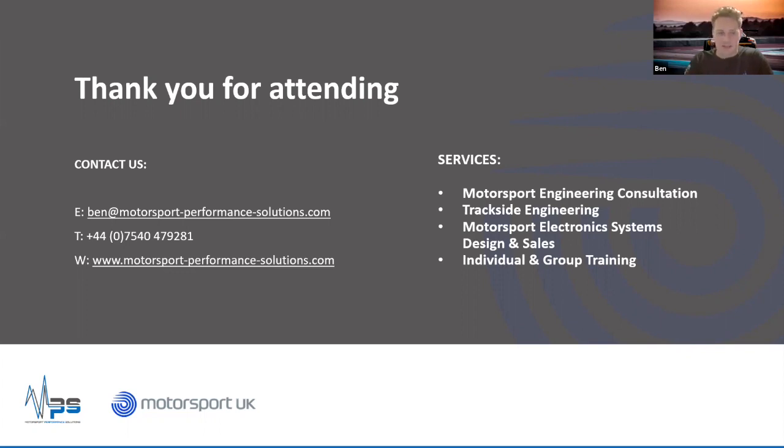But as someone that's sort of the intended audience of this, people that have never used driver data or any sort of data analysis before, you don't have to worry about being that accurate to still be able to productively use the results, if that makes sense. So the key thing with mounting, though, is to ensure that the accelerometer can't move, which would definitely induce erroneous values, and then you couldn't trust the trends, you couldn't trust the shapes. So I hope that makes sense.